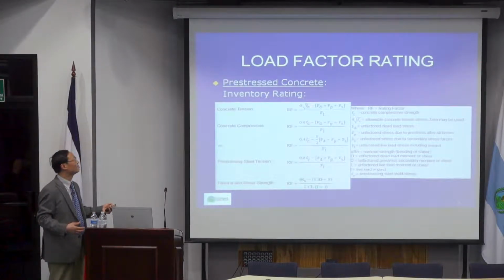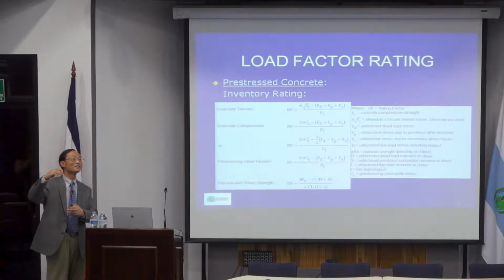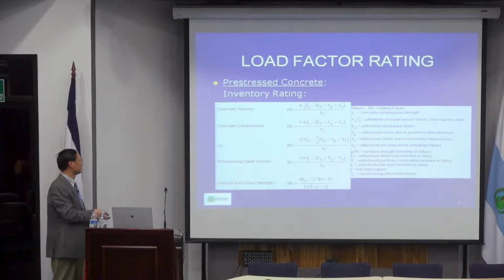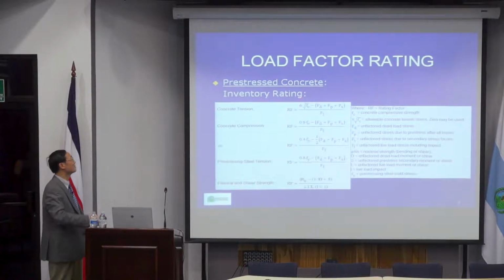So that's why my allowable stress, subtracted by these permanent stresses, gives me how much stress I can use for the live load. Then that's the live load stress, and that will give you the rating factors. And the compression is the same. Also for post-tension, the pre-stress steel itself has 0.8 Fy as allowable, minus permanent, and divided by the live load. So that's also for the stress itself, so that the concrete won't crush or crack because of overstress.